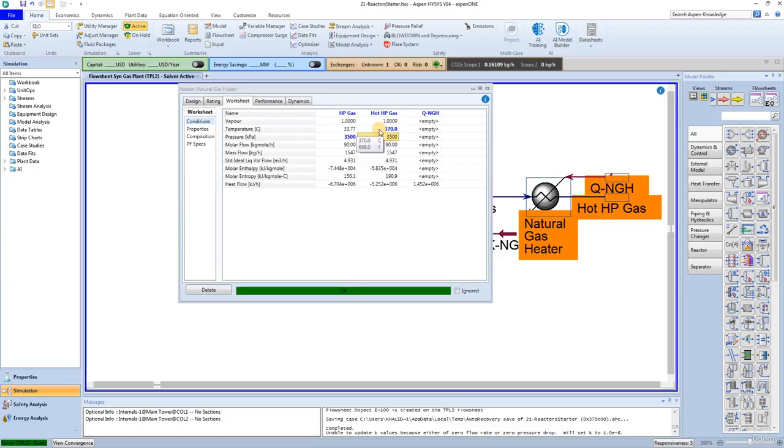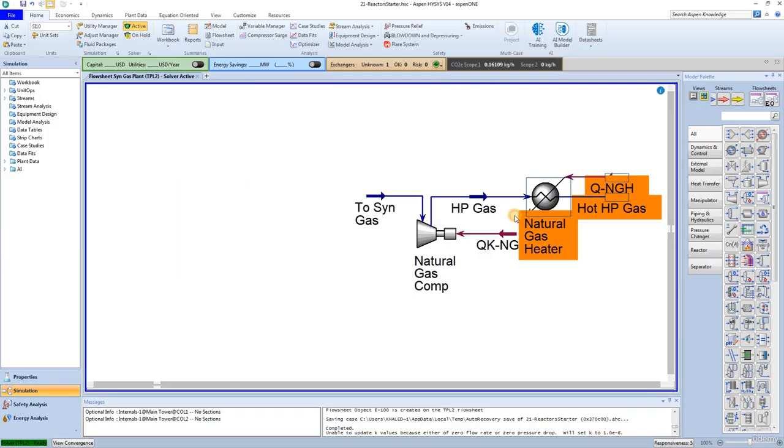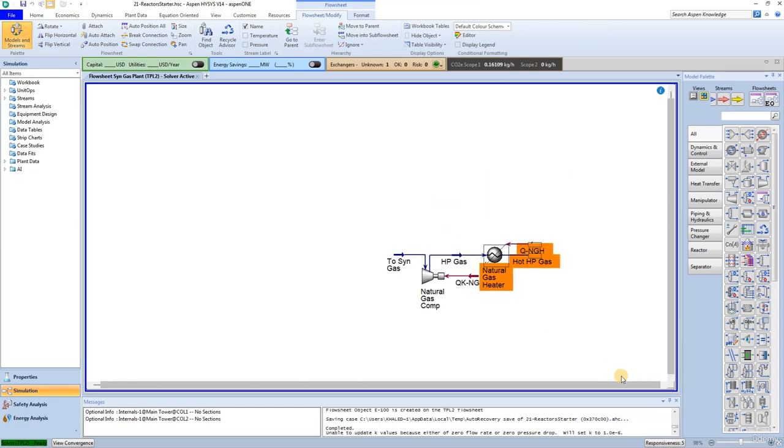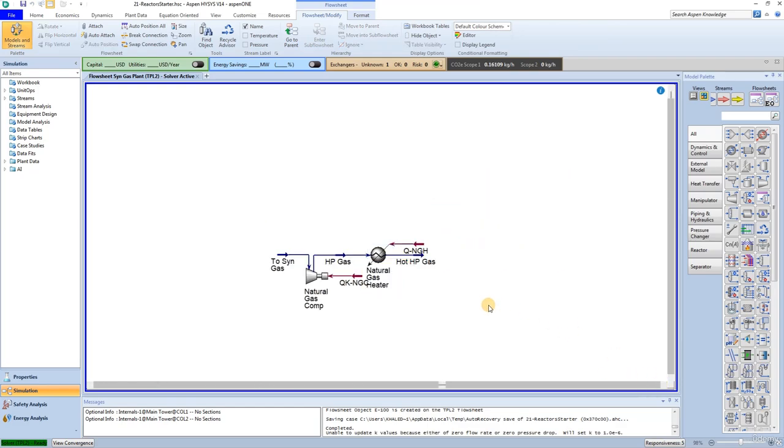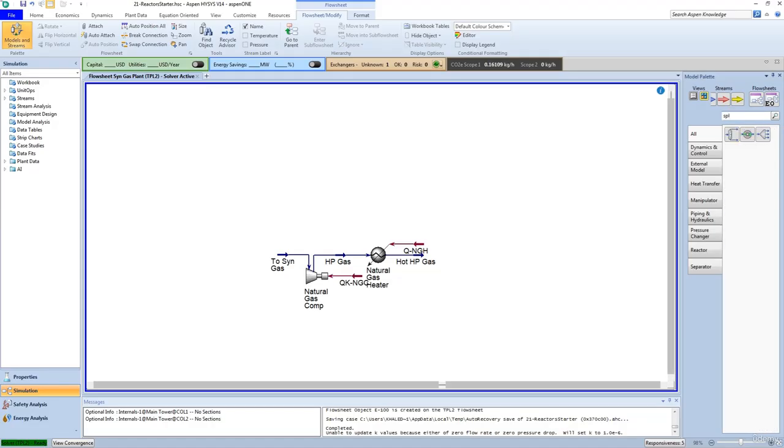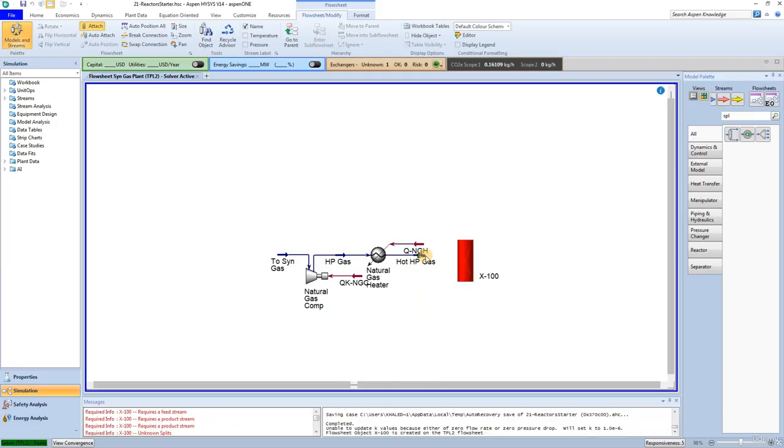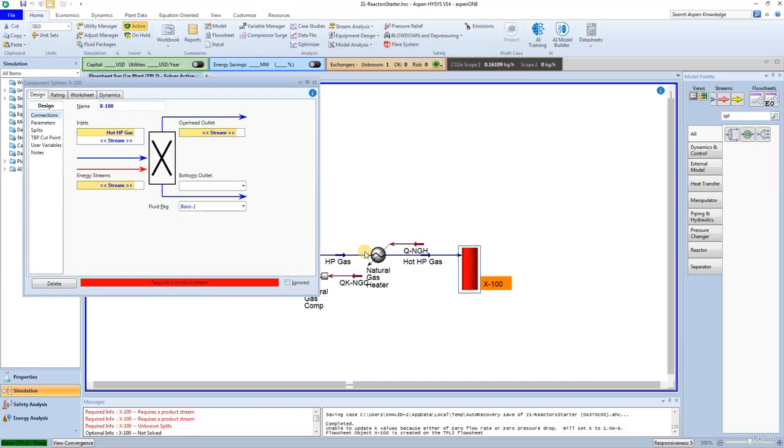The last step before setting up the reactions and reactors is to remove all hydrocarbons heavier than propane from the reactor train feed. Add a component splitter. Define the overhead and bottoms outlet and energy streams.